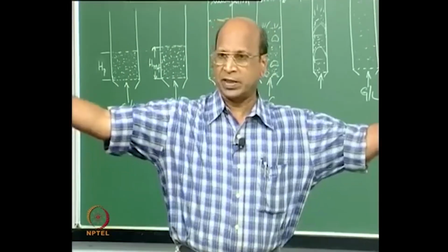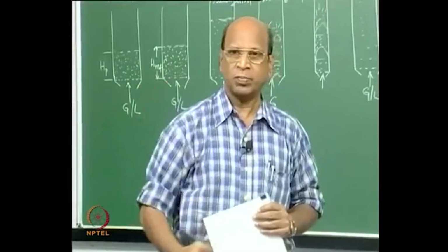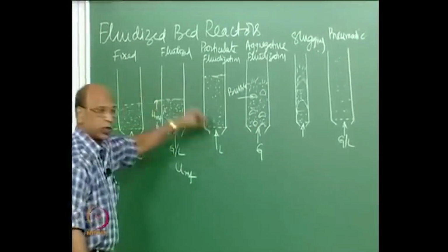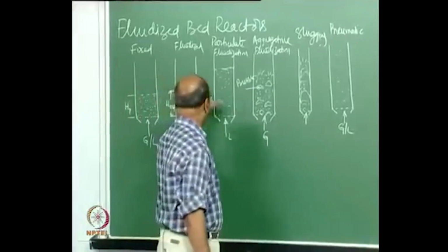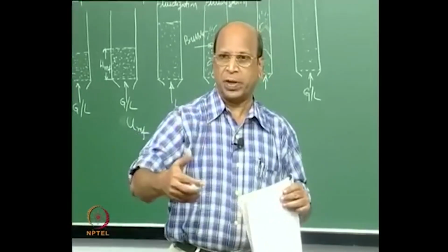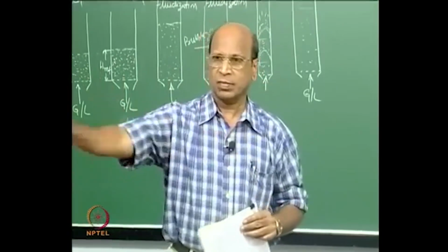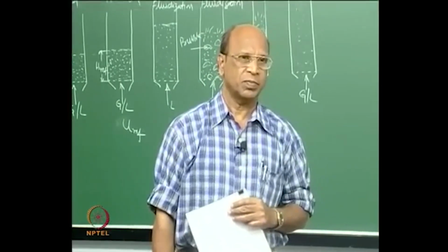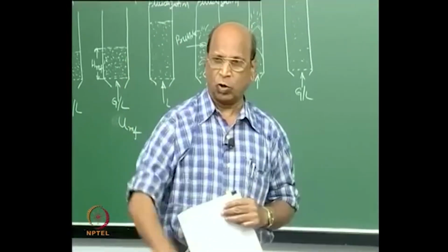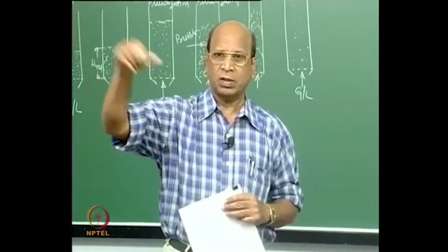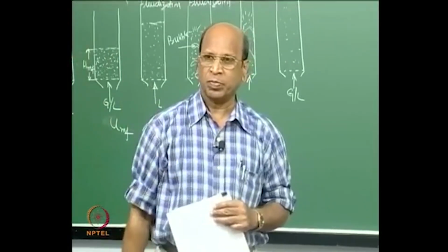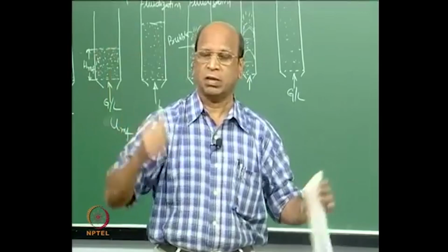What they do is, they take very big size fluidized beds, fluidize coal, and continuously feed the coal. I have told here batch only, but continuously also we can do that experiment, nothing will change. Okay? If you are maintaining the same bed and all that. So, coal particles will be continuously fed and burning, combustion is taking place. Now, you put inside heat exchangers, cooling coils. They are not actually cooling, they are water pipes, water tubes. So, then water will get evaporated to steam, that steam will come out after getting sufficient steam, then that is attached to your steam turbine, the turbine is attached to a generator, from there we will get AC and all that.